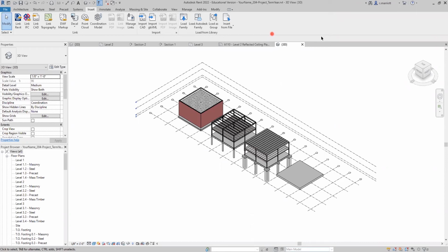Gradually, they've begun to integrate glulam in this, but mass timber is a newer term, and it applies to some of the more fabricated components, including glulams, but also things like cross-laminated timber floors and wall panels, and that sort of thing. It's also associated with taller buildings that exceed what you can do under the normal type 4 HT designation. So even though our structure is only 2 stories high, we are going to apply some of the components that would be associated with mass timber.